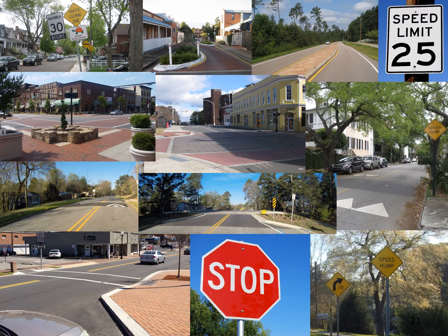And we've got to think about also the spacing of these elements or these slow points to maintain midpoint speeds of 25 miles per hour. So if you're looking at trying to keep people at 25 miles per hour in between those slow points, the spacing of those slow points can be no more than 300 to 400 feet apart. So we can't just put one of these elements in on a long roadway and expect for speeds to stay low.